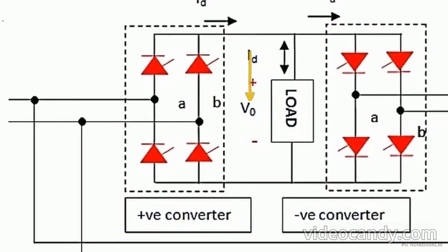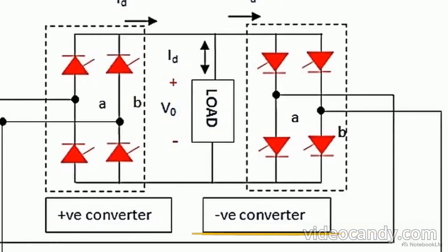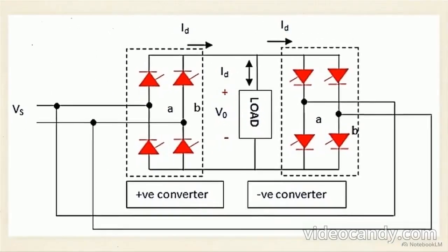The control circuit fires the thyristors in the positive block over the span of several fast input cycles. By controlling their firing angles, this group synthesizes a sustained envelope of positive voltage across the load. Once that positive envelope is complete, the firing pulses shift. The right block takes over, producing a sustained envelope of negative load voltage by driving the current in the opposite direction. There is a strict operational deadband required here.